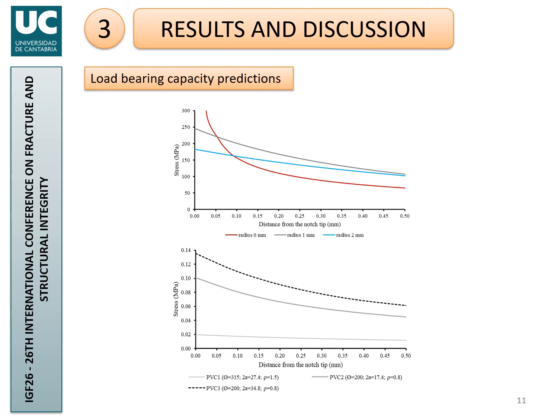Again, these are the stress fields at failure of the fracture calibration specimens. And by obtaining the average values of these crossing points, we obtain half of the critical distance and the inherent strength. Half of the length should be around 0.07 millimeters, and the inherent strength should be a bit lower than 200 megapascals.